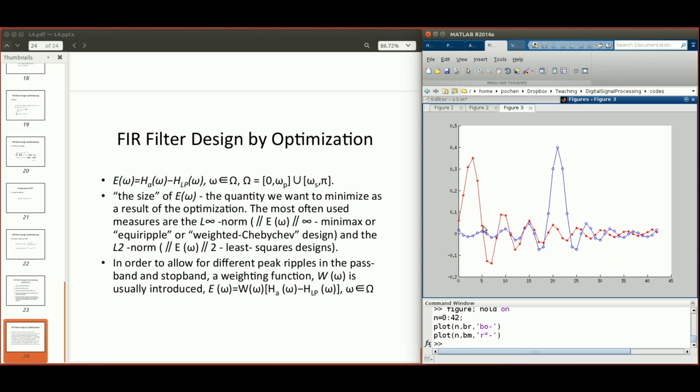For a minimal phase filter, it's certainly not a symmetric function anymore, right? It's not a symmetric filter anymore, right? But you can sort of see most of the big amplitudes are kind of clustered close to 0. It's actually a typical behavior for minimal phase filters. It has minimal group delay. We're gonna talk about what group delay actually means, right?